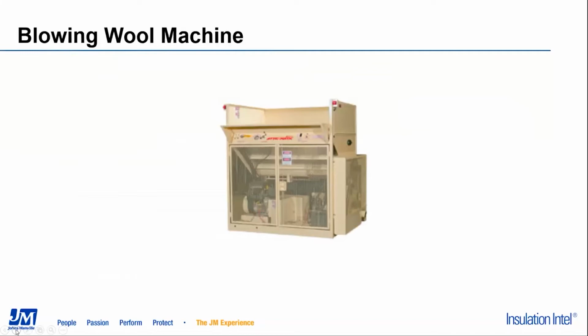So the blow machine is our delivery system. Bales of blowing wool are placed in the hopper and go through a series of paddles that break up the material and start processing it. Material then falls down into a rotating paddle wheel and is blown through the hose into the job where the applicator will install into the cavity.